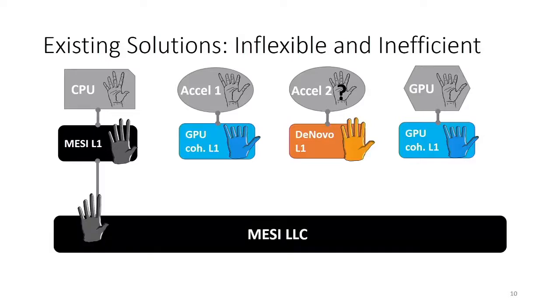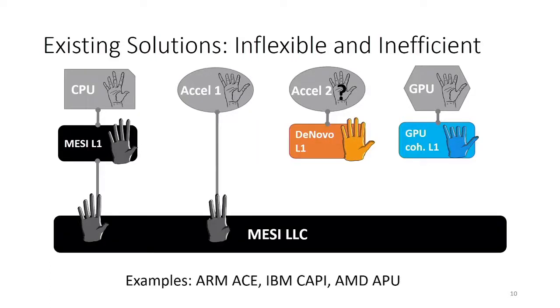Okay, so today, this integration is quite expensive. In particular, the standard temptation is to use CPU-style protocols at the last level of your cache hierarchy to integrate all of these devices. And this is partly because we are familiar with these CPU MESI-style protocols. So for example, if I have a device that already does MESI, this is awesome. You just connect it to my last level cache.